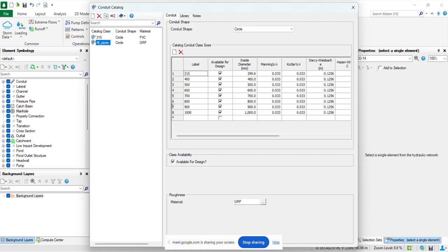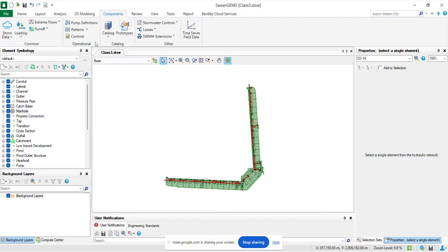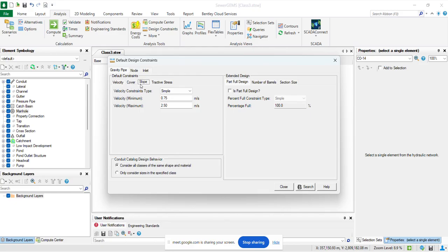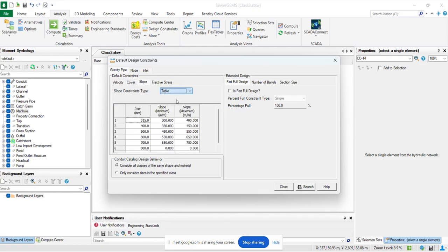For the bigger pipes we can go for mild slopes. For that purpose only we are defining here. Did you get it, Abhinaya? Yeah. After 600 it is better to go with the same slope.